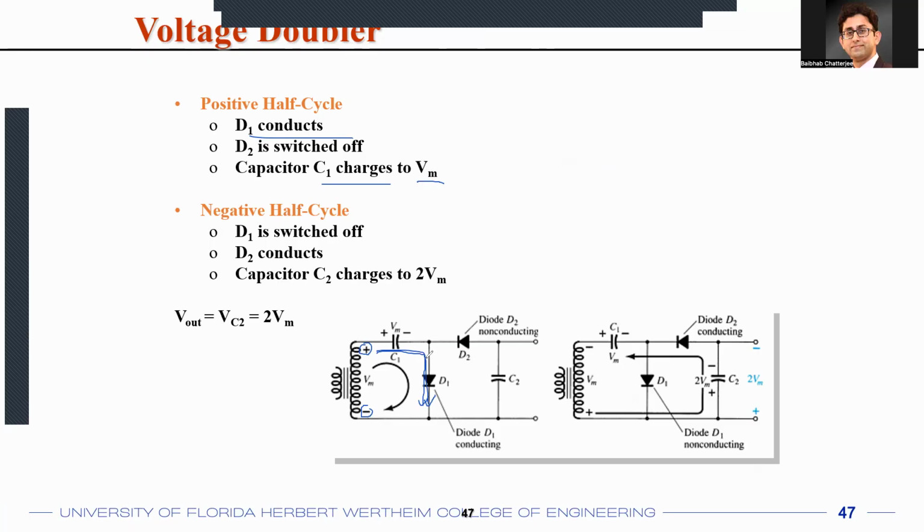So of course, the voltage drop has to happen across the other component, which is the capacitor in this case. The same thing that we had seen earlier for the clamper circuit as well. That when the diode is forward biased, because the voltage drop across the diode is 0, the voltage has to drop across the other component, which is the capacitor in this case. And that capacitor voltage is equal to Vm.